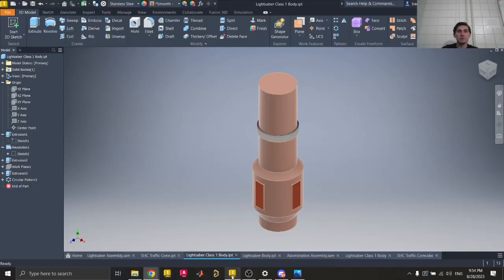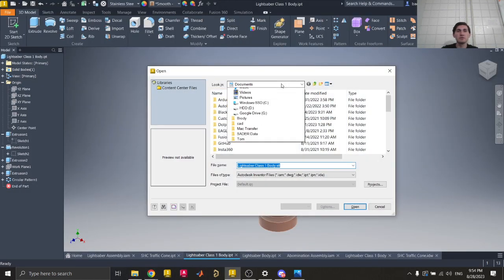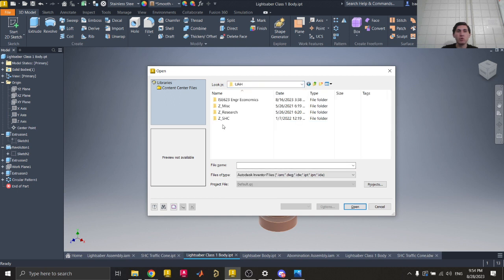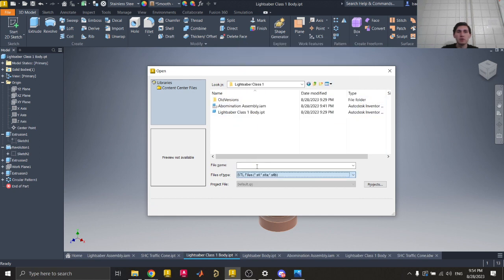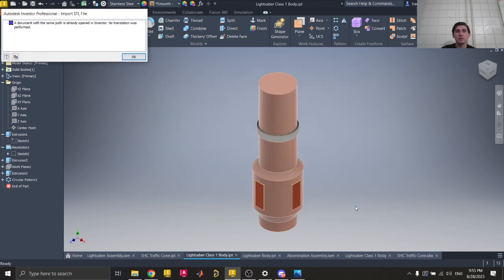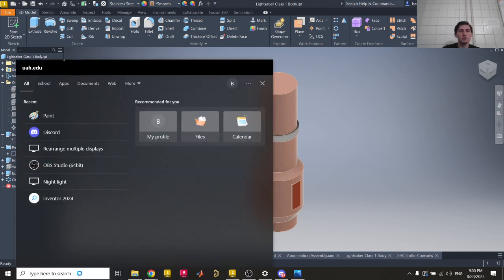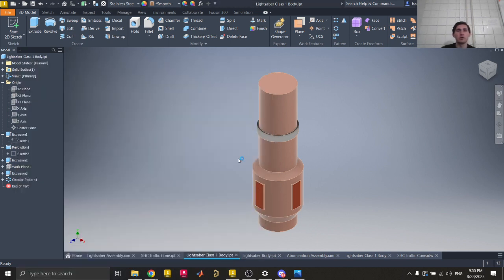So I'm actually going to open up that STL. Let's go to Cura. Give it a second. What it does is that lower resolution is going to turn circular elements like this into polygons, and it might look kind of blocky, and it will show up on your print, and it's not going to look that good.